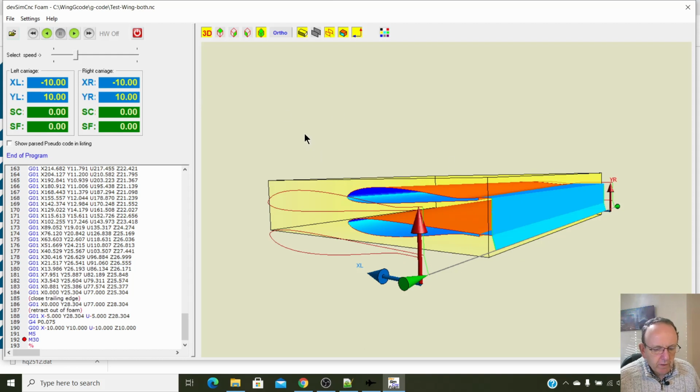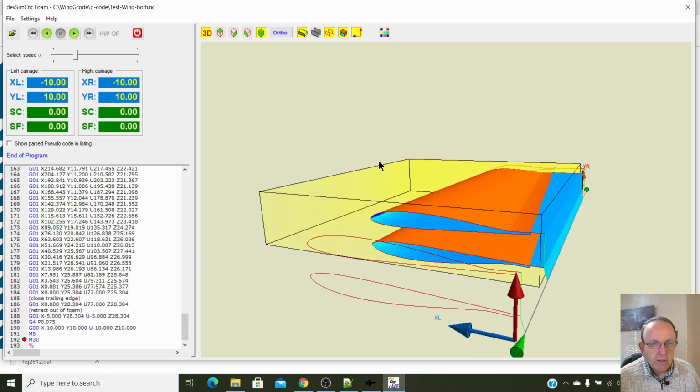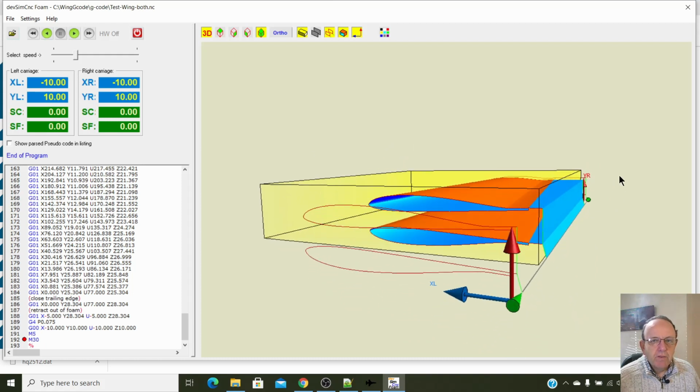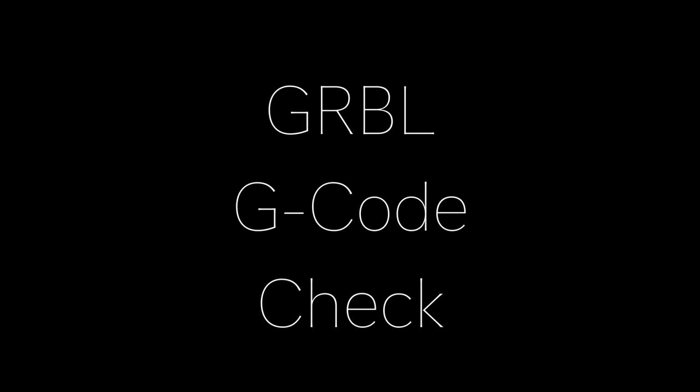So this is a real good program to check to make sure your Gcode is okay first, because what you don't want to do is put your Gcode in, find you've got some setting wrong, and drive the axis into the stops and cause some damage. So that's what we're going to do, check it like that. I've got my test Arduino here, which I can just plug in, and it will simulate being connected to the foam cutter. Let's see if we can get plugged in. There we are.